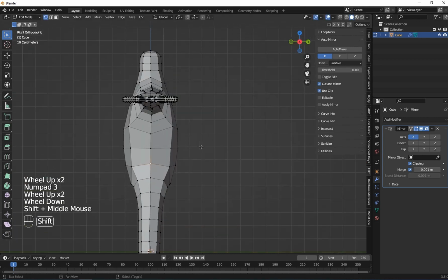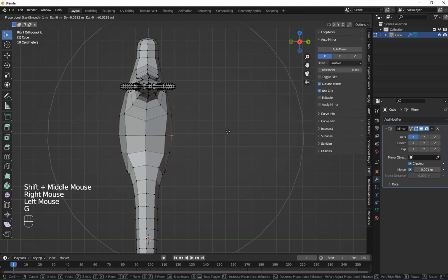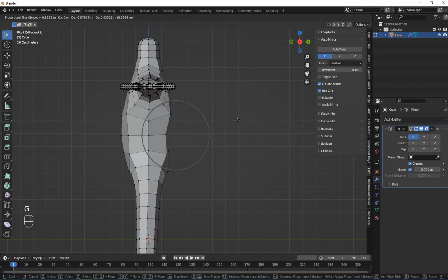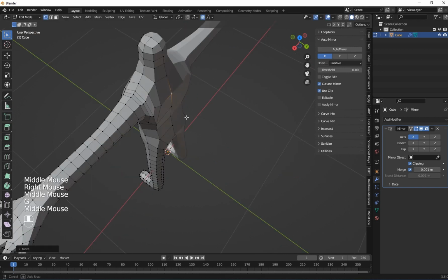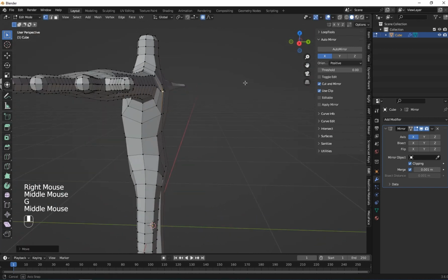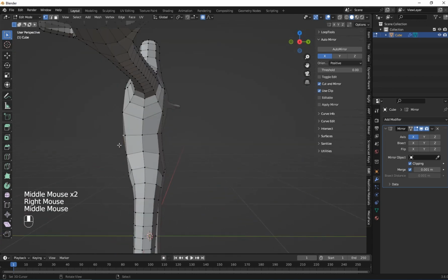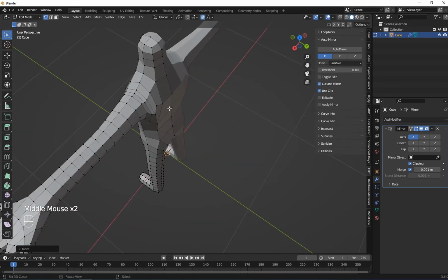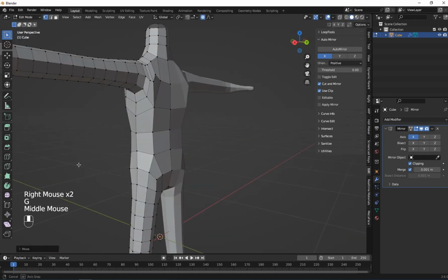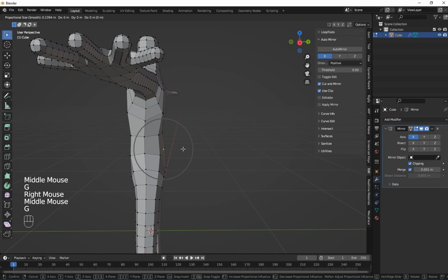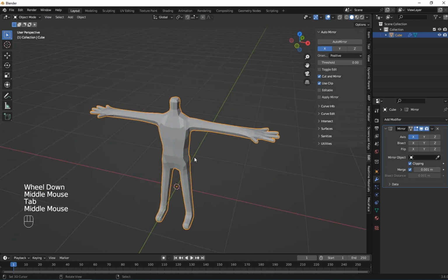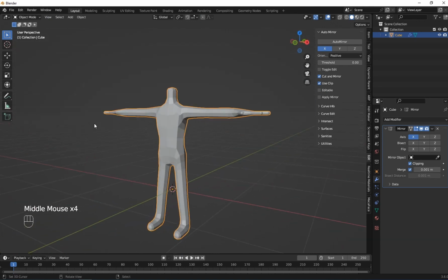Press 3 to go to side, right view, and go to shape. So I'm going to use proportional editing. So use your mouse scroll here to increase or decrease the radius, and let's line it. Yes, so I'm going to add a subdivision modifier to it.